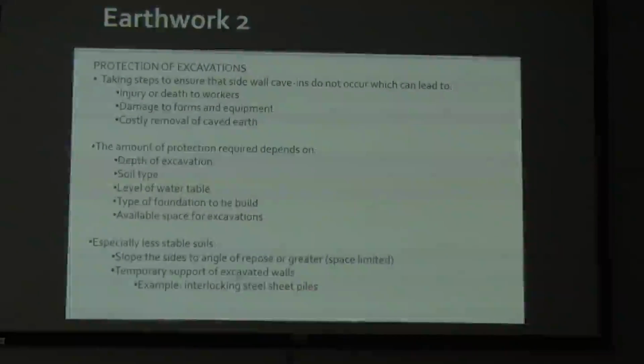The temporary support of excavated walls, we'd have to support them temporarily. An example of that would be interlocking sheet piles, which we see a lot of down here, particularly on vertical construction when we're excavating the foundations. The interlocking sheet piles can be used for a couple of things. One, to hold the side walls of the excavation in place, but also as a means of a water barrier.